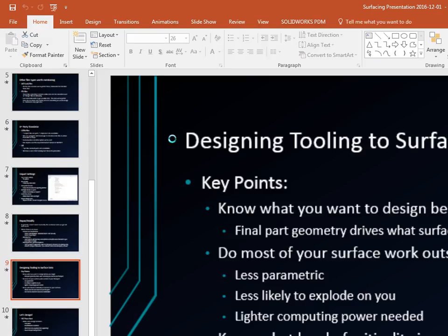Okay, well, let's see. I think this is going to fail too. This is a bad example of move face. Sorry. It's not your ready-made SolidWorks what's new example. I've had it where I frequently had to delete the radiuses, then move the face and add the radiuses back in. Yeah, if I go before the fillets, it'll probably do it. That's a good point.